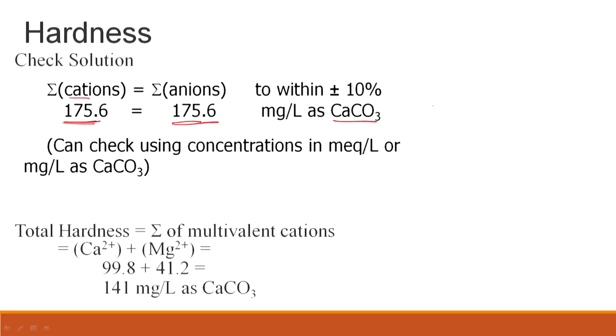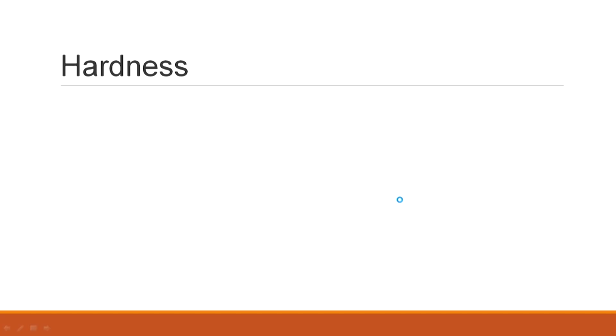Right, and then we will move on to calculating total hardness, which is the sum of the polyvalent cations, and typically it is going to be calcium and magnesium. So, in terms of units, we say milligram per liter as CaCO3. So, we see that this is the hardness, and this is typically on the lower side. In, let us say, Roorkee, we typically have 250, in other parts of India relatively higher, I guess.